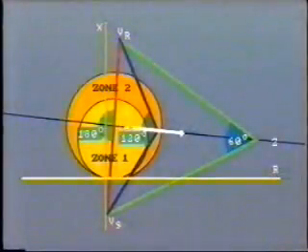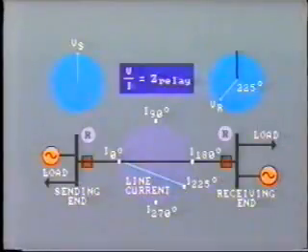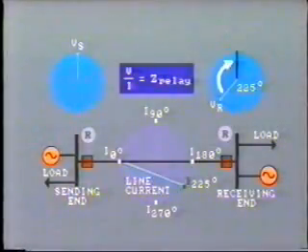That is, moving through the first zone and out into the second zone again. The impedance increases because the current flow in the line is now decreasing again as the swing continues. At the receiving end, voltage is now beginning to close in on the sending end voltage and so reduce the angular displacement.